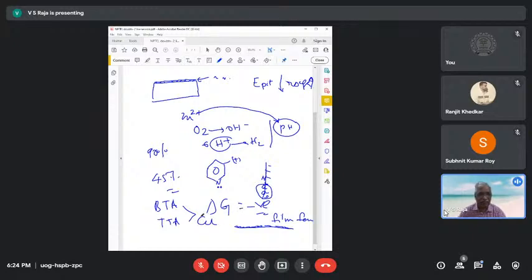So instead of taking one molecule which is a poor mixed inhibitor, I will take two molecules: one very good anodic inhibitor and one very good cathodic inhibitor. I put them together, and it works far better, right? Rather than taking a mixed inhibitor whose efficiency is not that great. So this is how the industry works to control corrosion.